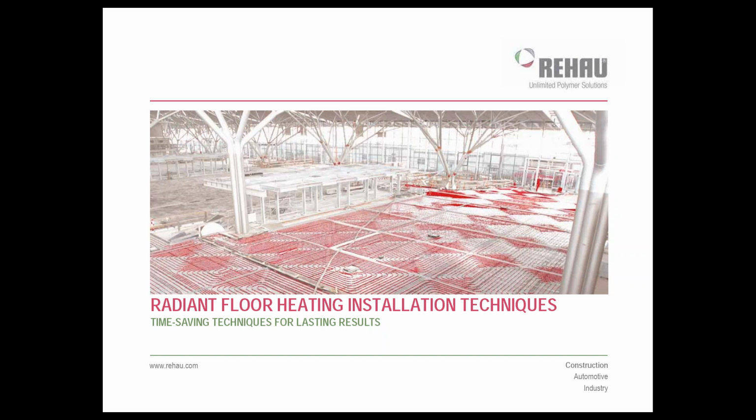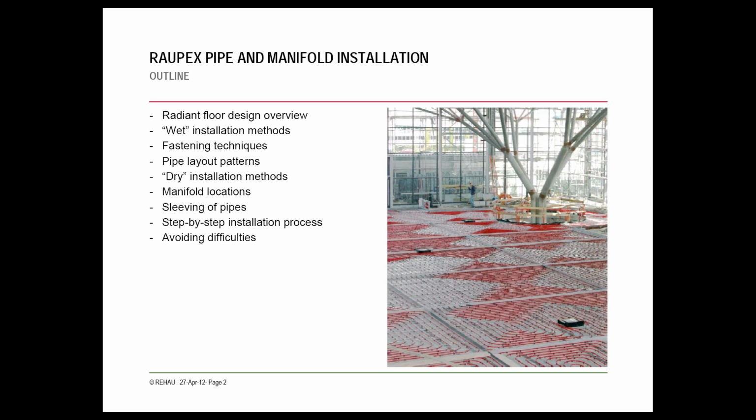I don't see carpet over radiant very often, unless it was like a throw rug or whatnot. But carpet definitely puts a big damper on your output. So that's something to be cognizant of as well, going forward with the install here.